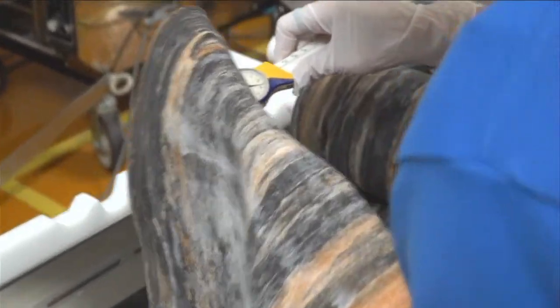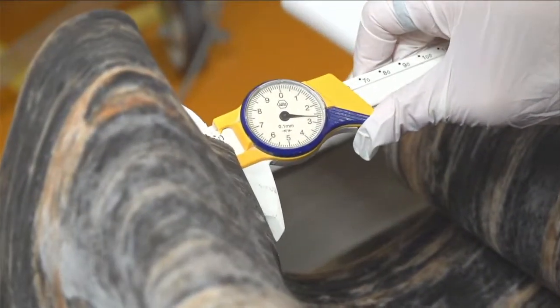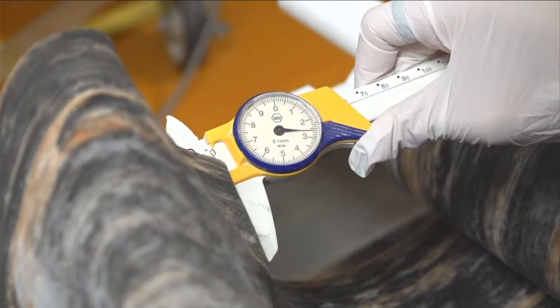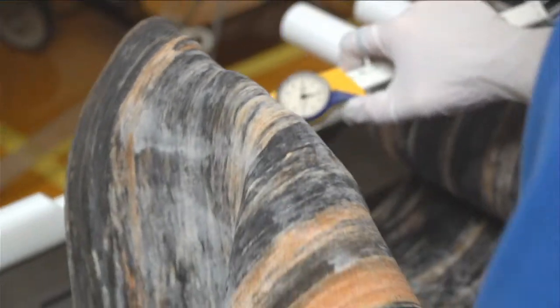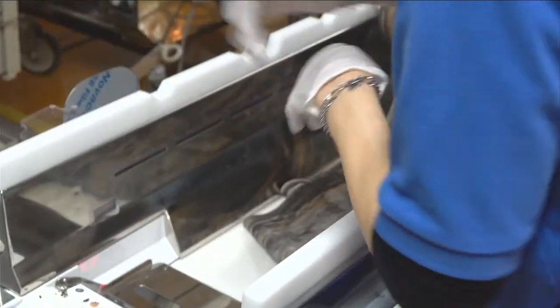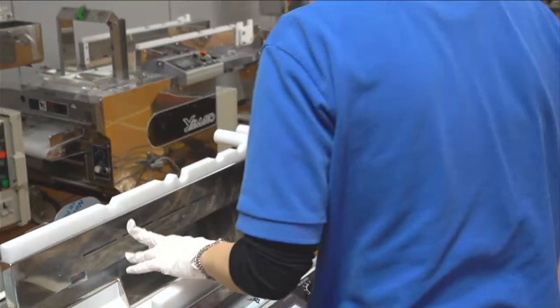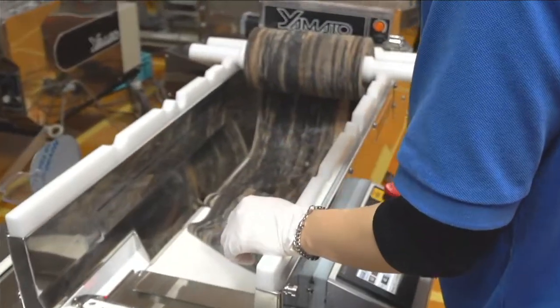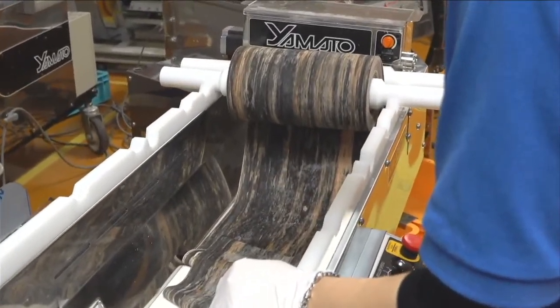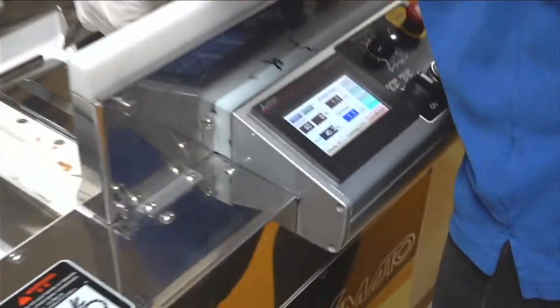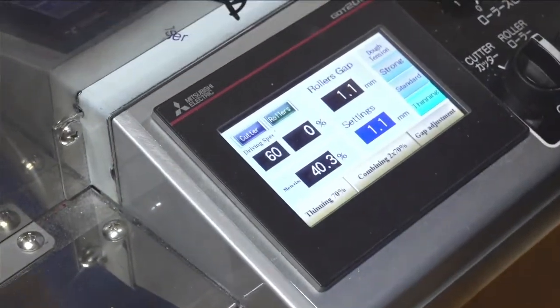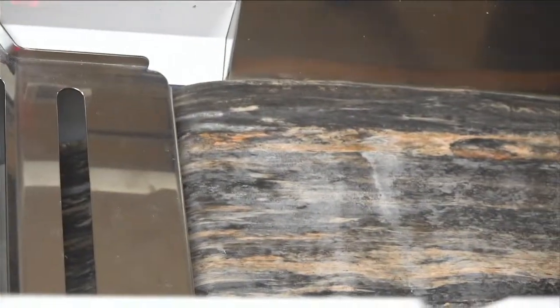And then I will talk about this: the actual thickness is always bigger than the roll gap, 2.56. So we know the difference between the roll gap and the actual thickness is 0.6 millimeter. By knowing this, we can set the roll gap appropriately to get the final thickness right.